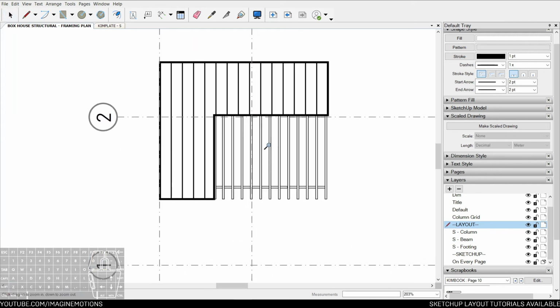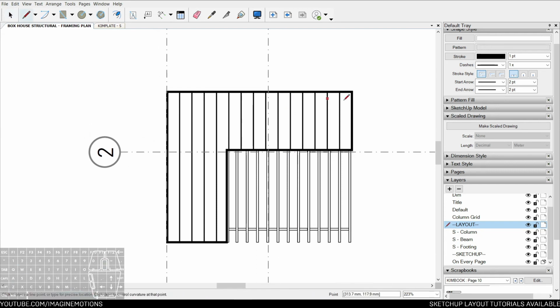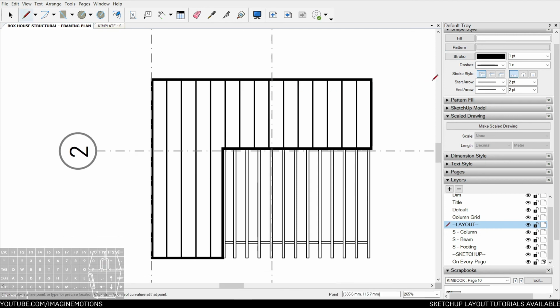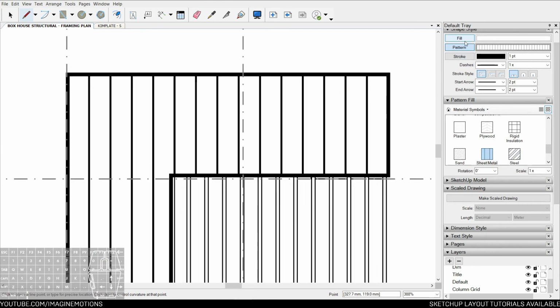So since this is a bit confusing, and let's say I made a design that I want them to follow, I could make a section cut and plan view by using that pattern. I remember we have something called sheet metal for our roofing. Oh, there it is. Okay, so let's say I'll turn on the fill, make something like this.